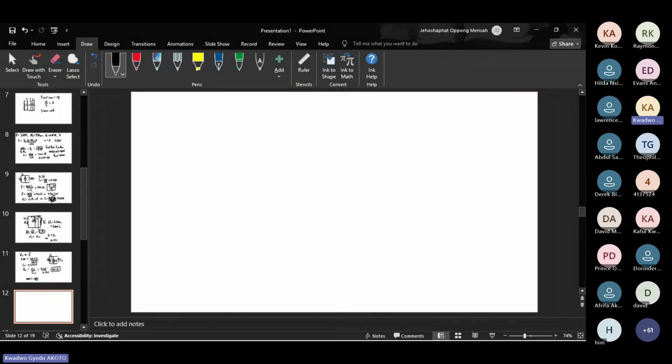We are going to look for our E at full load conditions, right? Because at full load we are going to be generating a high E so that once our IA, RA losses come in, we can still have a high terminal voltage. So we know that V is equal to EA minus IA RA, right?